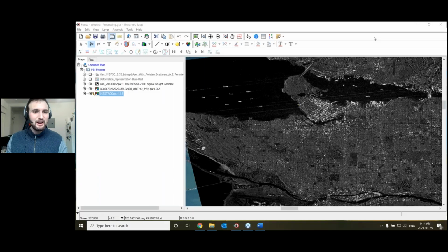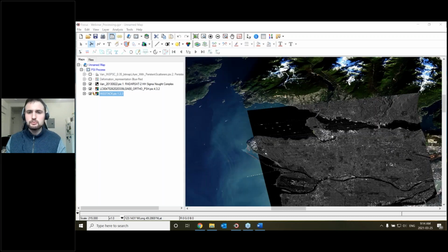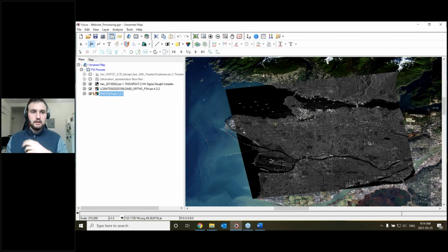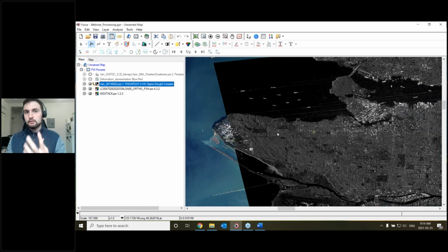Wonderful. Alrighty, so what we have here is just one example of the ingested images processed underneath a Landsat image. First, working with an SBAS approach, we employed that to identify the interferometric pairs based upon the perpendicular and the temporal baseline.